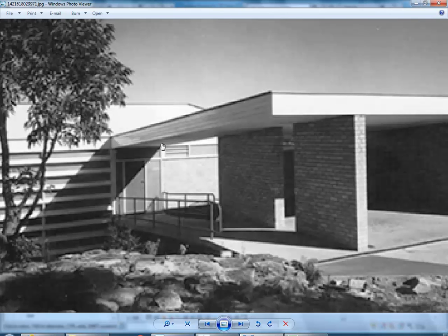But when you've got a situation like this where the window goes all the way across, I've just found it's easier if you put a curtain wall on top and have that wall stop at the bottom of the window. Because it gets a bit complicated. If you're cutting a hole that goes all the way through from one side of the wall to the other, it's then a bit difficult to work with that wall.